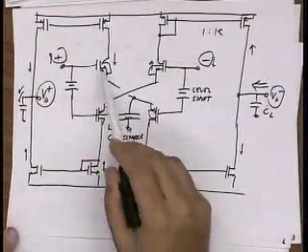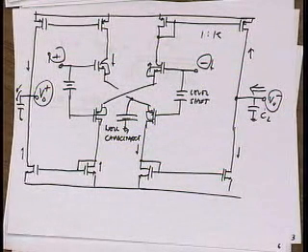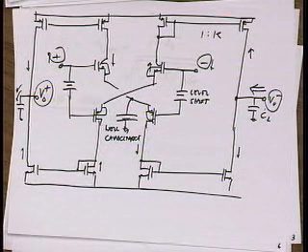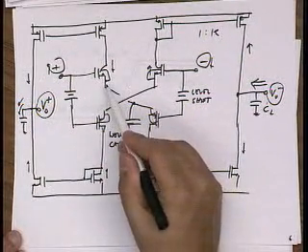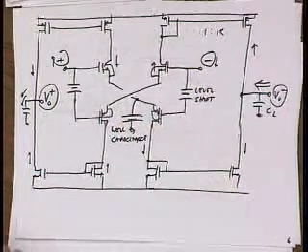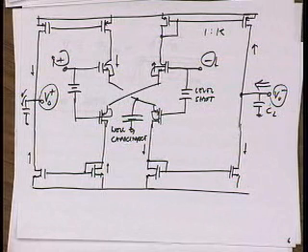We're probably going to tie these to ground. If you tie them to ground, though, are we going to have problems with the body effect? In other words, if this source voltage moves, that generates a current in opposite polarity to the gm, so it's going to reduce the gain.